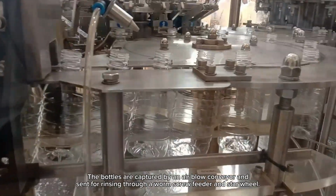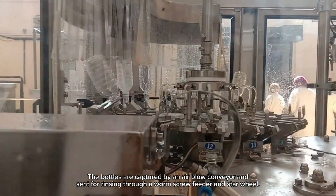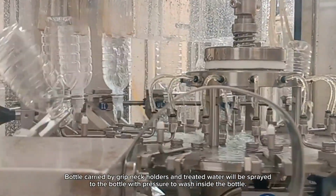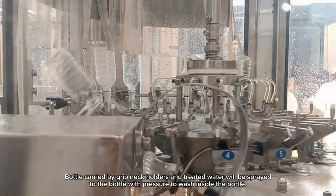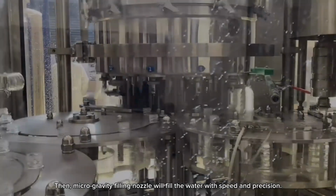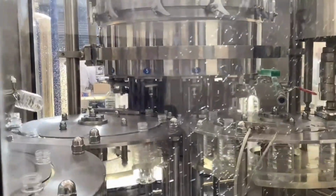The bottles are captured by an air blow conveyor and sent for rinsing through a worm screw feeder and star wheel. Bottles carried by grip neck holders and treated water will be sprayed to the bottle with pressure to wash inside the bottle. Then, a microgravity filling nozzle will fill the water with speed and precision.